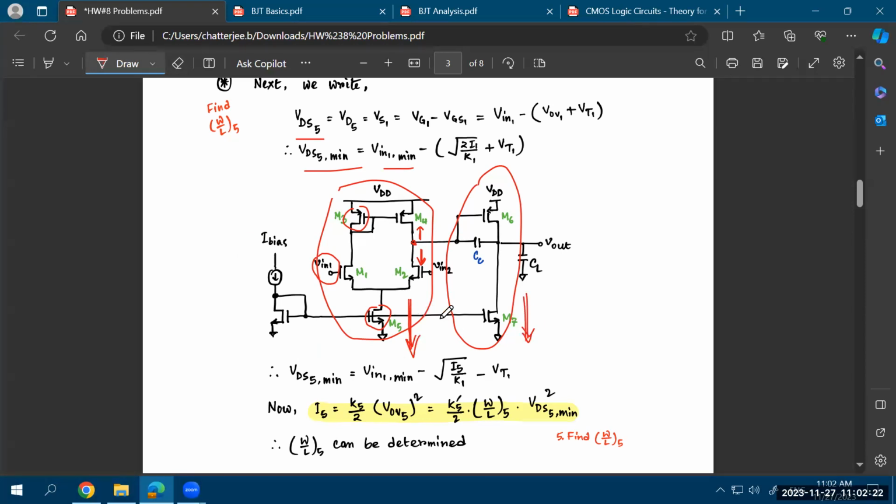So the current being consumed in these two stages multiplied with the supply voltage. So for example, in this case, the supply is basically VDD, because on the other side, you have a ground. So multiplying the total current with VDD will give you the power consumption, because power is voltage multiplied with current. Okay. But if you had a VSS, let's say you had -5 volts instead of this ground, then the power consumption would be the difference in voltages between VDD and VSS.